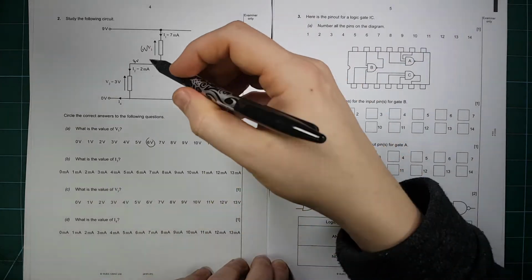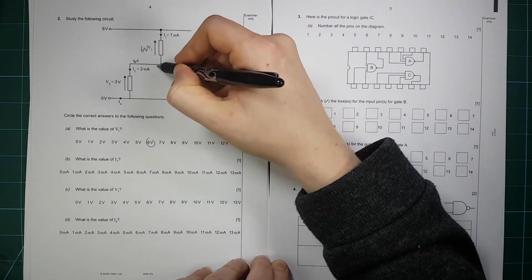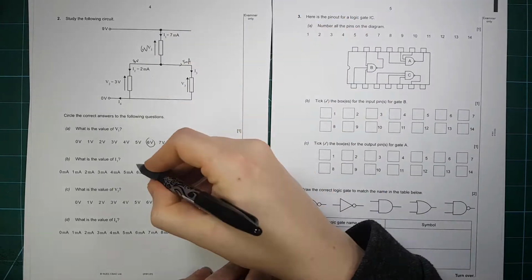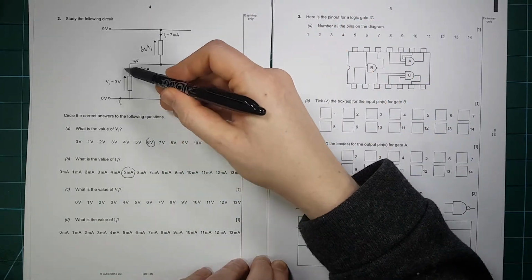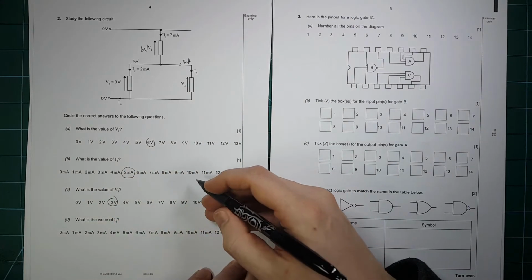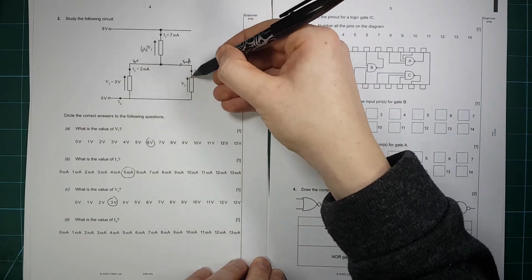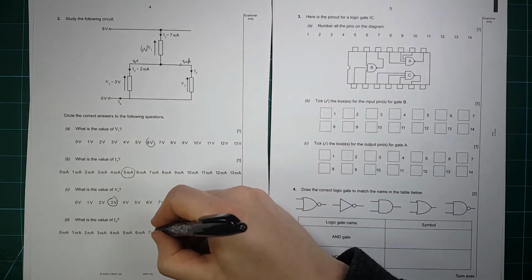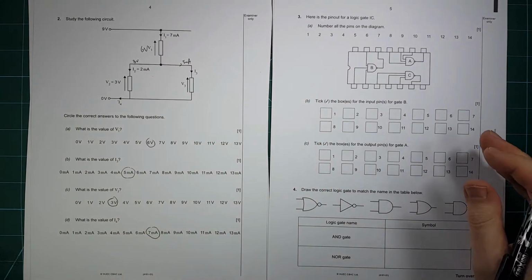What is the value of I3? That's this one here. We've got 7 milliamps coming down here. If 2 go off that way, then 5 milliamps must go on that way. What's the value of V3? V3 is in parallel with V2, so it's got to be the same, so that's 3 volts. And what's the value of I4? Well, that's all the current joined back up again. That current there joins with that current there, so it's 2 plus the 5, which is 7 milliamps, which has to be the same as the current entering there.